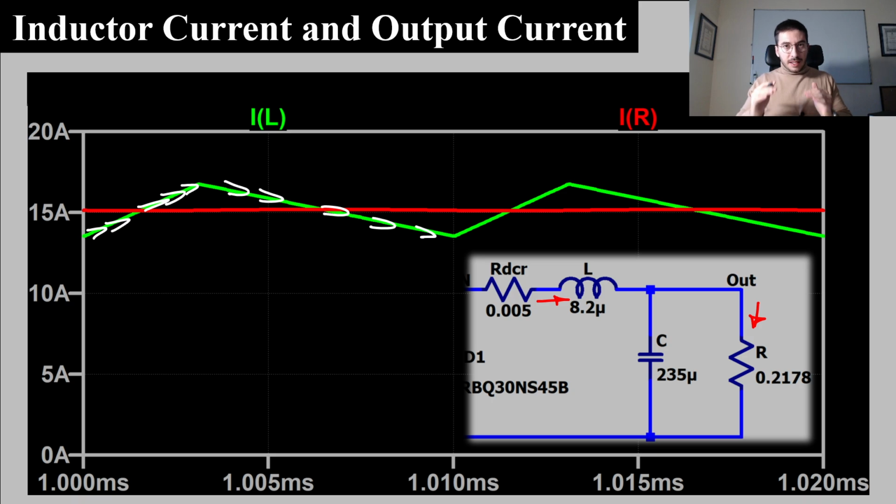What happens if you check the waveforms in detail? You will see that there are small differences. For instance, if you check the peak-to-peak current ripple in the inductor, you will see that it's not exactly the same value due to the reasons that we have explained before. But in general, until this point, the conclusion is that the results are very similar.